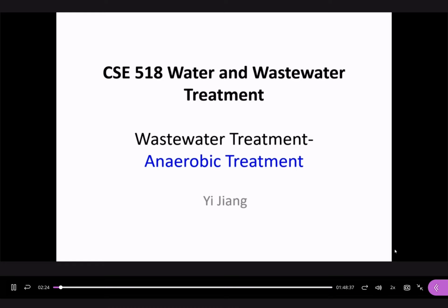So what do we do under anoxic condition? Reduction, right? Reduction reaction. We have nitrate, right? And it ends up with nitrogen. So nitrate is the electron acceptor. Positive 5 to 0, the oxidation state for nitrogen. From positive 5 to 0, that's reduction. Nitrate is the electron acceptor.